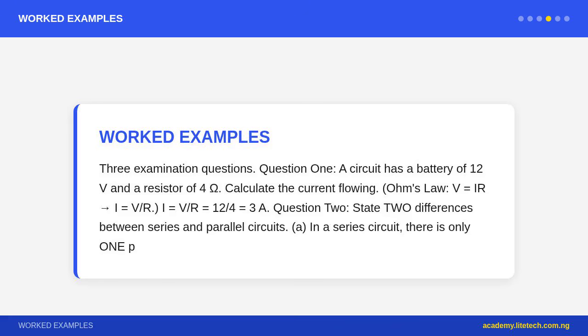Earthing or grounding means connecting the metal casing of appliances to earth, or ground, so that if a fault makes the casing live, current flows safely to earth rather than through a person.